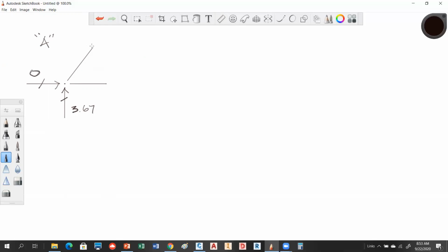I have to decide whether these guys are in compression or tension. Okay, I don't know that. But the key here, and truly, it doesn't matter because the math is going to tell you if you're wrong. So if you called something tension and you get a negative number, it's saying no, it's compression, and vice versa. Okay, so if you look at this diagram, though, it's pretty easy to figure out.